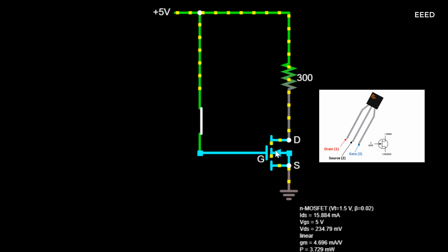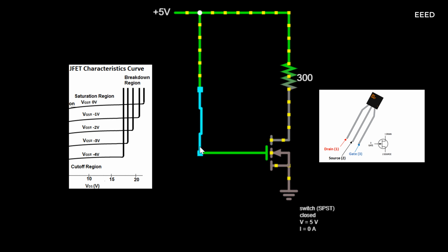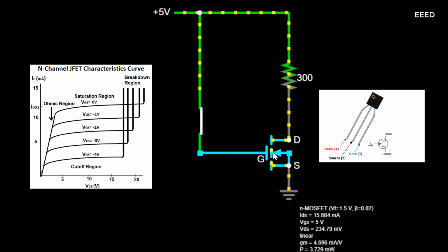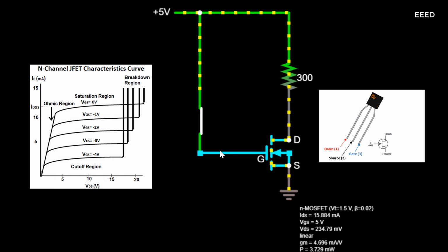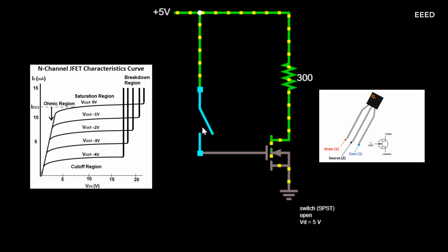The characteristics curve of an N-channel JFET transistor shown below is the graph of the drain current, ID, versus the gate source voltage, VGS. This curve represents the transconductance, or simply the gain, of the transistor. The transconductance of a transistor really means the gain of the transistor. So this transconductance characteristic below shows the gain of the transistor, how much current the transistor outputs based on the voltage input into the gate terminal.